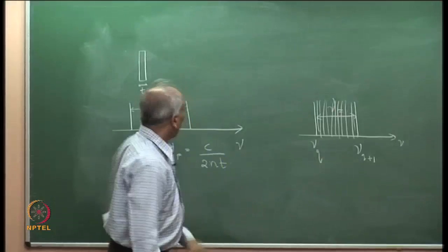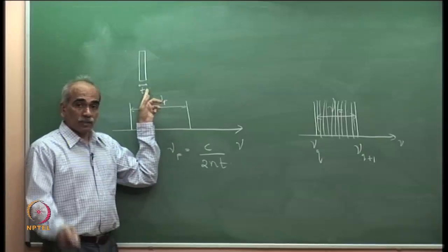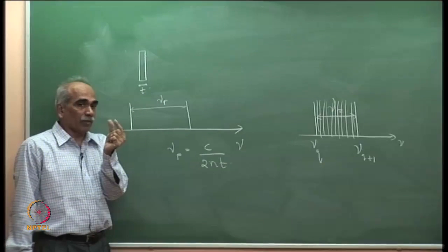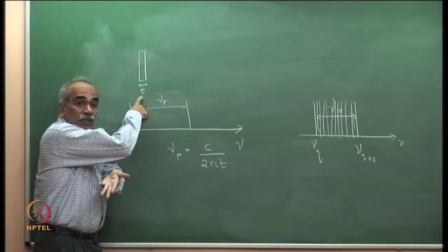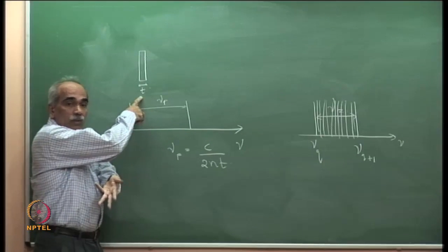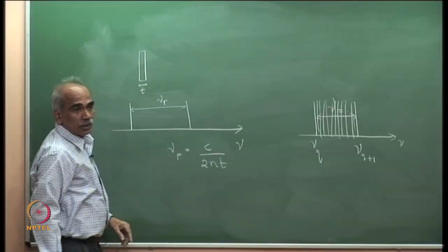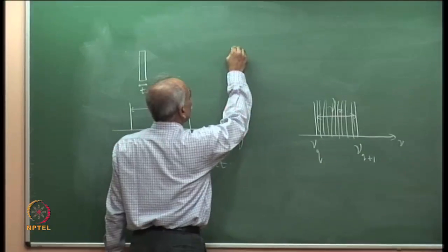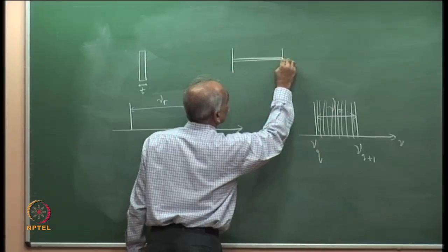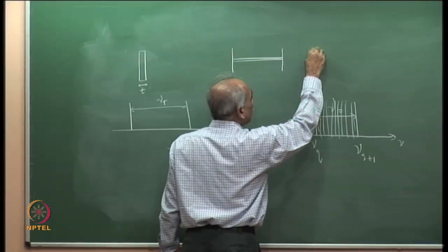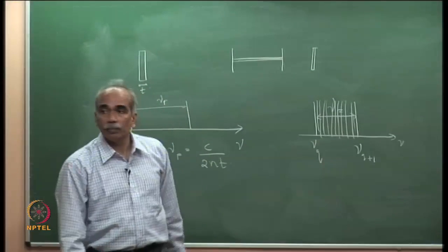Of course, this is for normal etalons in bulk optics, but in semiconductor lasers t is already 300 micron. So, if you want to use an etalon which has a larger spacing, this t should be 10 micron or 20 micron or 50 micron, much smaller t's. If you take smaller t's, then the separation can be large. So, you have two cavities coupled. Please see this: this is one cavity, the semiconductor laser cavity, and there is an etalon here. Why tilted? I will tell you a little later. Just a couple more minutes, we will stop.